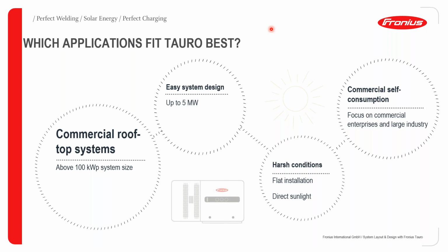So with the Fronius Snap inverters that are also available for commercial installations, you do know of the requirement that if you're going to have the inverter exposed to maybe more than 4 hours of sun heat per day, we do recommend a bit of a shelter or roof to be built on top of the inverters. So that has nothing to do with ingress protection. It only has to do with the buildup of heat within the inverter, which therefore starts derating after a certain limit of temperature is exceeded. With the Fronius Tauro, this is not going to be a problem because of the double wall concept, and therefore this inverter can operate in direct sunlight or sun heat conditions.